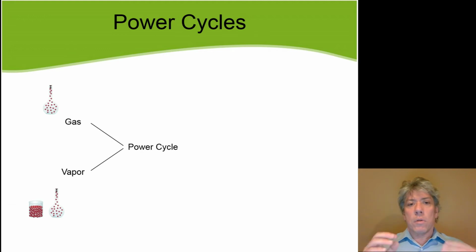And so this water has gone from the liquid phase into the vapor phase, and of course after going through the turbine and pushing the turbine blades, so it's literally steam doing work, it's steam pushing the blades, that's the working fluid therefore. When that steam is done and it exits the turbine at a lower pressure, then it goes into a condenser where it is cooled down.